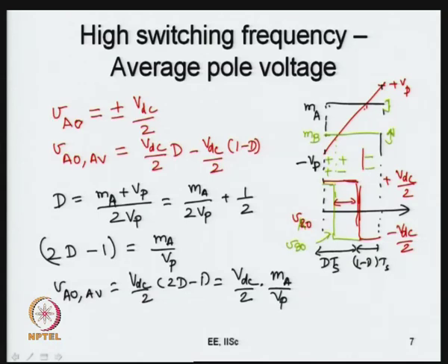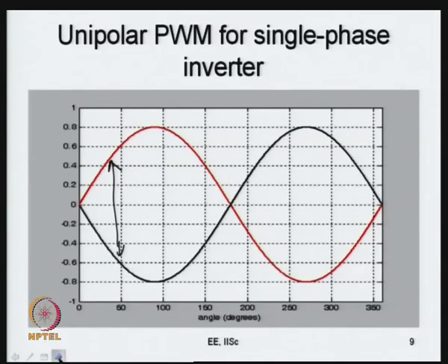So, you can apply 0 voltage to the load either by switching both the top devices on or both the bottom devices on. So, when you are adding common mode voltage, the time for which you are using both the top devices and the time for which you have both the bottom devices conducting changes. That is why I said it is related to the redundancy. The redundancy is what lets you add such a common mode voltage.